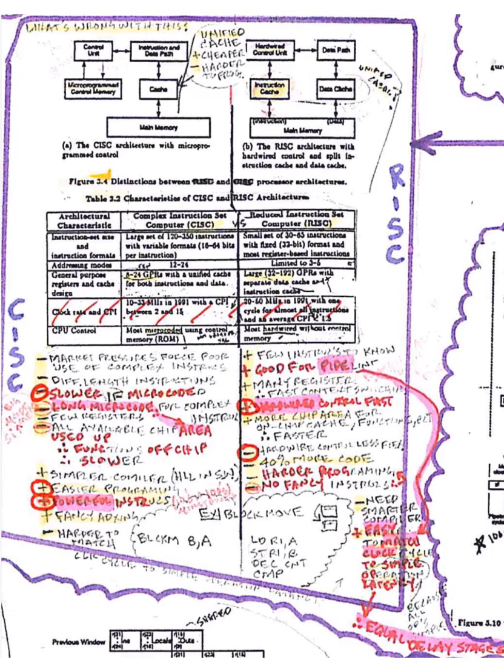There's microcode, actual nanocode, very complex thing. Inside IBM, we had that for the large-scale systems because they were CISC, and you wanted to be able to change instructions over time and even put in a patch on a $1 million machine somebody bought 10 years ago, update the instructions. So if they're micro-coded, which they can be in large systems in CISC, then it's slower because you have to interpret all that. If it's hardwired, it's going to be faster, as you see over in the RISC.